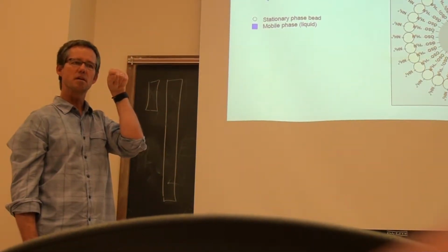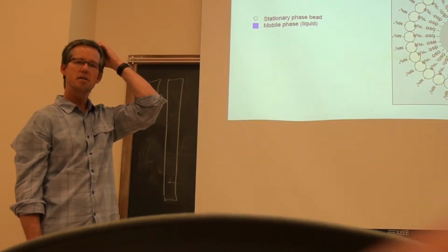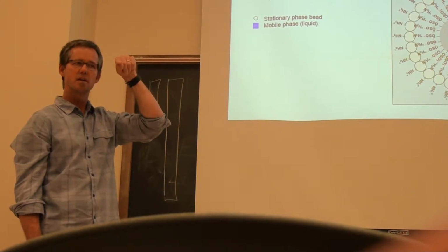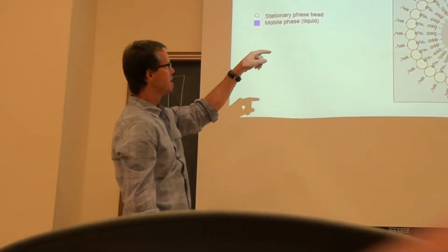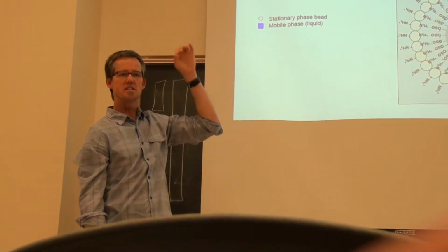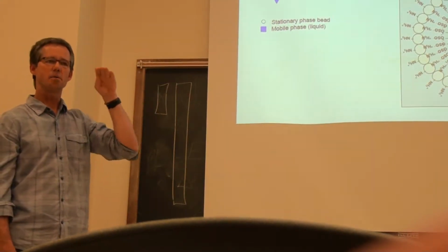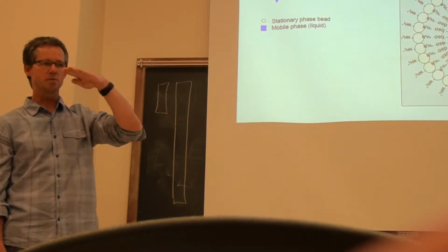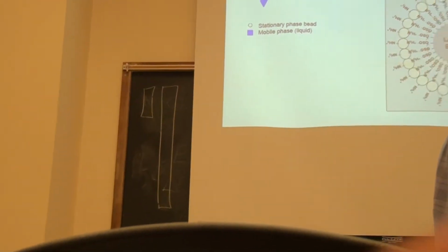but the tubing is this PEEK tubing that's about maybe 0.1 millimeter in inner diameter. So really skinny tubing, the inner diameter is really skinny, that's attached with these high pressure fittings onto a column that generates these special pumps that are able to generate high pressures without leaking and without generating any pump noise. It would generate a sort of an oscillating background signal.